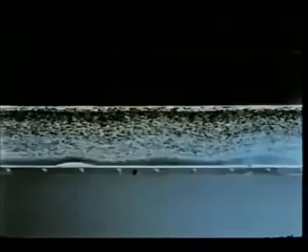If we drop the internal Froude number below its first critical value of 1 over pi, simple sine waves appear in the lee. These internal waves are not possible in a homogeneous fluid. To see how they can arise in a stratified fluid, let's look at the vorticity equation for a frictionless, non-homogeneous fluid.